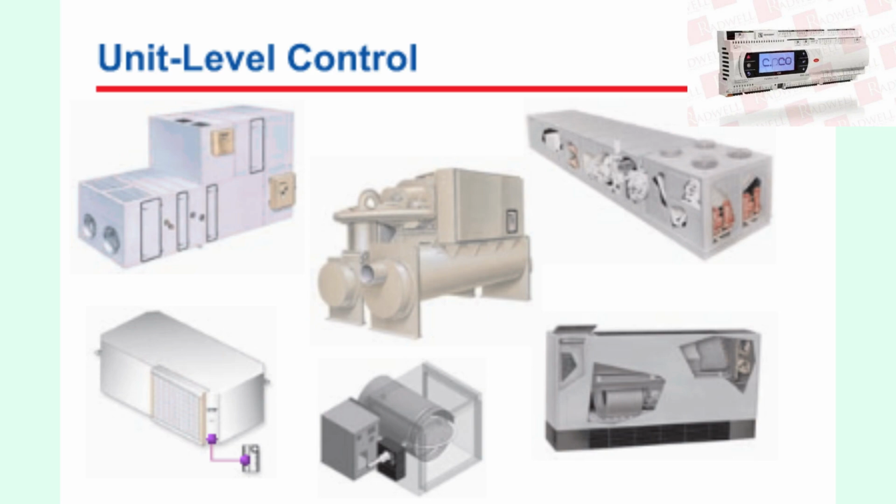Unit level control focuses on individual HVAC equipment, like air handlers, rooftop units, or fan coils. Each unit has its own controller that handles safeties, alarms, and set points. For example, a VAV air handler might include multiple control loops, one for discharge air temperature, one for outdoor airflow, one for static pressure, and even one for building pressurization. Each loop senses, decides, and acts automatically, keeping the equipment stable even if communication with the building system is lost.